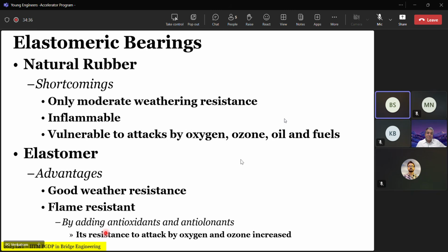Sir, I also think it is the wear and tear due to the environmental conditions. Wear and tear. Now I want you to be careful. Wear and tear requires a physical action, like rubbing, abrasion, and things like that. In this case, there is no wear and tear. There is damage, yes. That is why I want you to be very clear when you understand the definition. When you use the word weathering, don't use it in terms of the way you look at a wearing course. Wearing course will undergo wear and tear. Wearing course will not undergo weathering action.